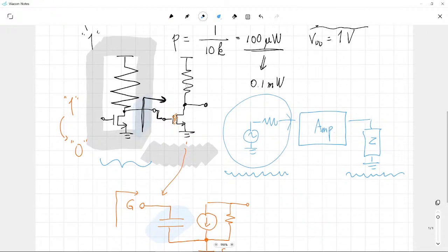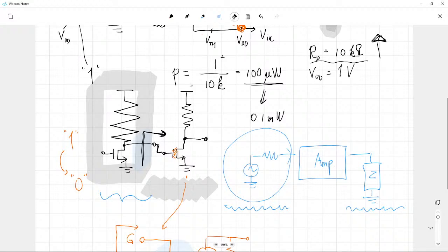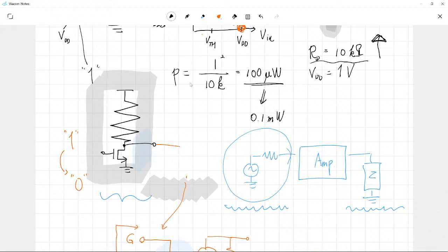So from the viewpoint of the central stage, all of the subsequent stages can be written as a simple capacitor C here. What is the physical meaning of this C? The physical meaning of C is the gate capacitance of your next stage. So now you have C here.